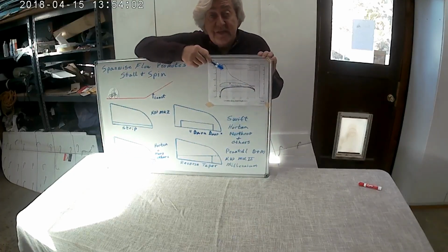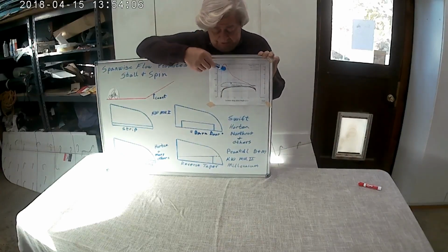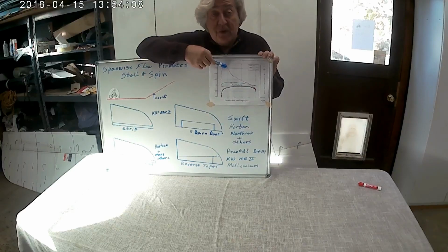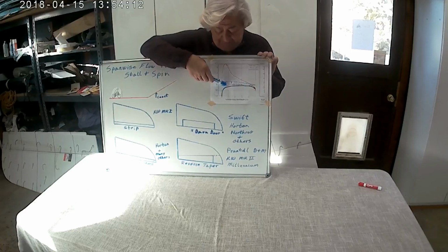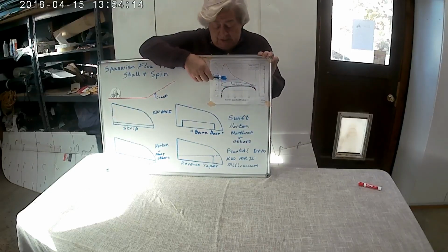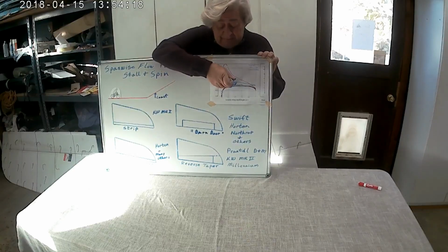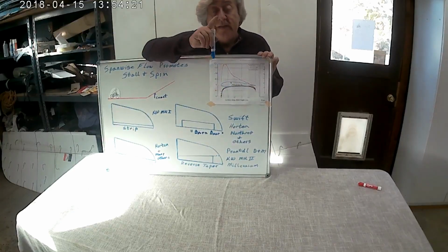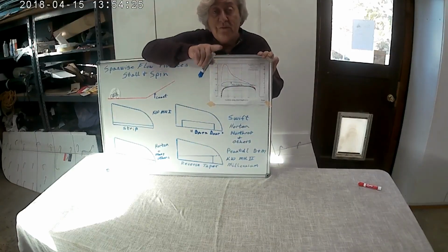If you understand pressure distributions on airfoils, you can see why I chose this airfoil. The peak of the low pressure is way up here by the nose. It's like in the first 10% of the airfoil. What that means is that the majority of your lift, the lift center of this airfoil, is far forward. And that's what gives it the nice neutral pitching moment that we want for flying wings.